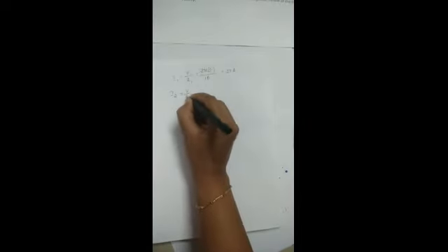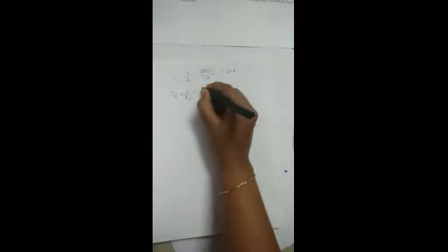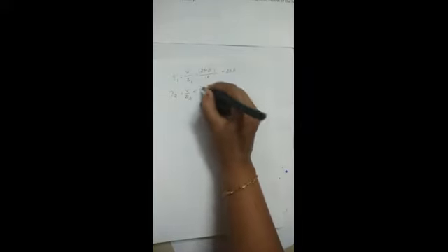This divided by Z1. How much is Z1 of this first branch? 10 ohm. So you can do it, and in the RLC you will get it as 23 amperes. Similarly, I2 will be equal to the voltage across this divided by the impedance of that branch, which is 230 volt, 230 at an angle 0, divided by Z2. How much is Z2?